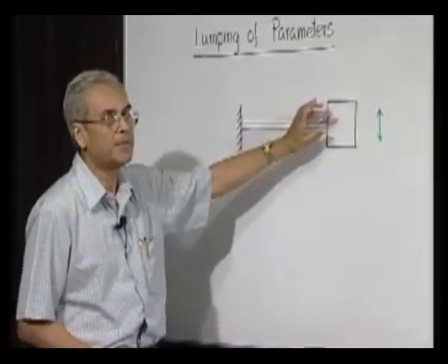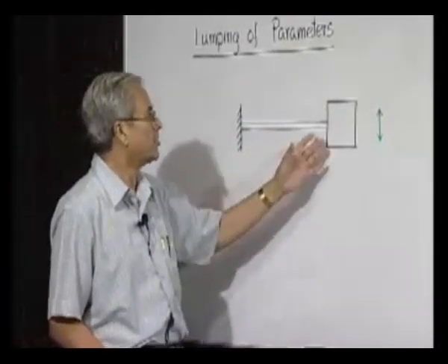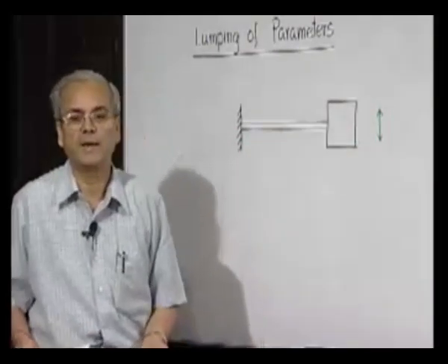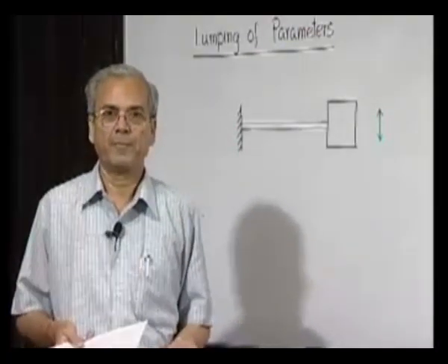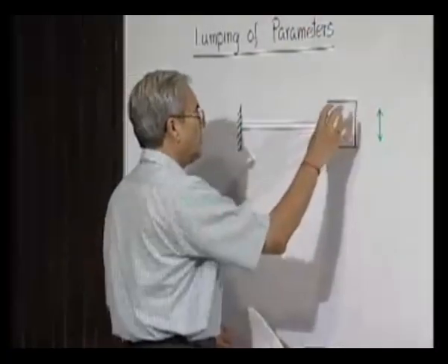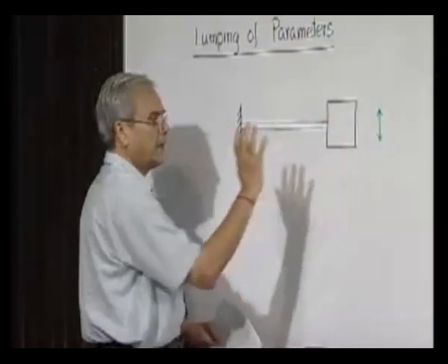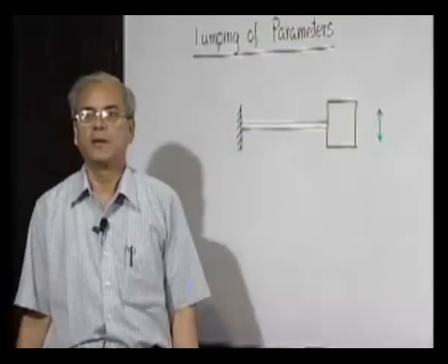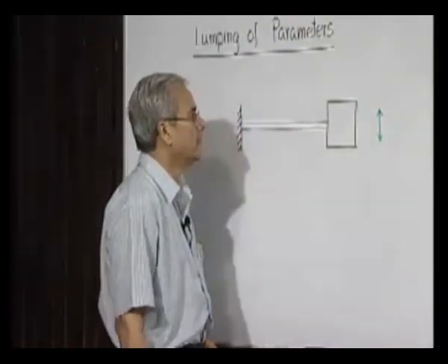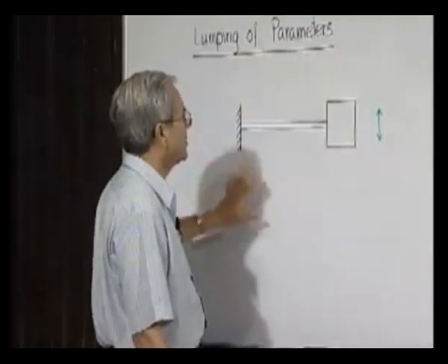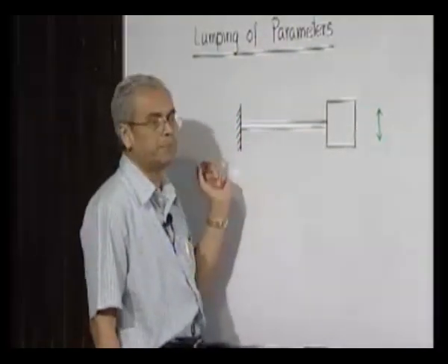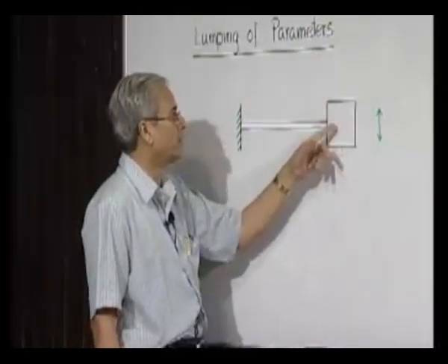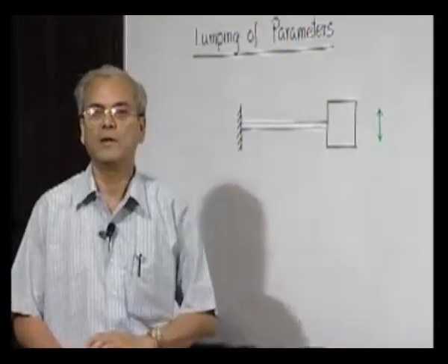It also has a certain degree of elasticity, but its elasticity is so negligible that its predominant role is just to provide inertia. So this is providing inertia, predominantly the mass. This is providing the restoration or acting as the spring, and the dissipation is because of the material damping in the beam, which is undergoing distortion, and friction with the surrounding air. All these things are causing dissipation.